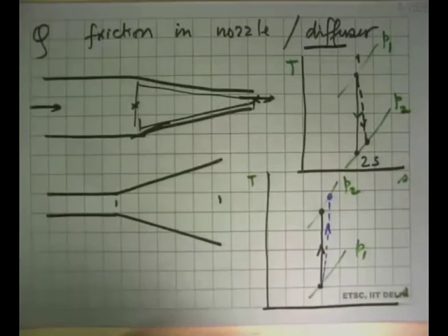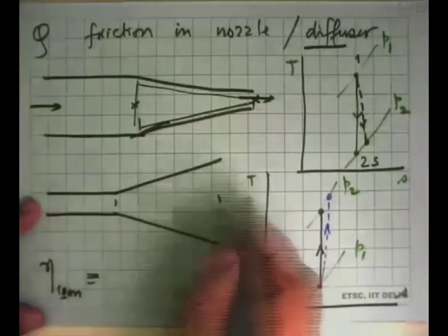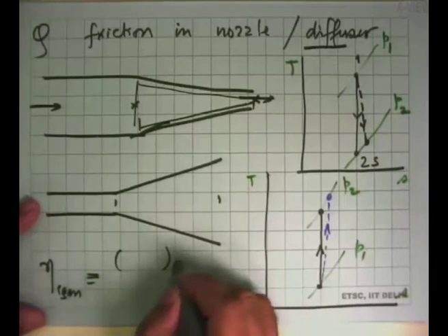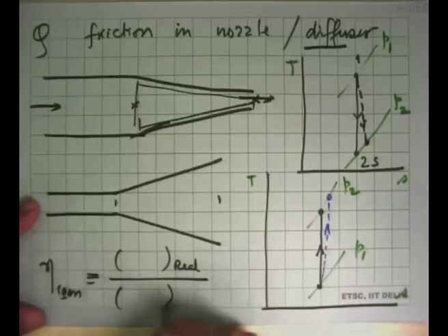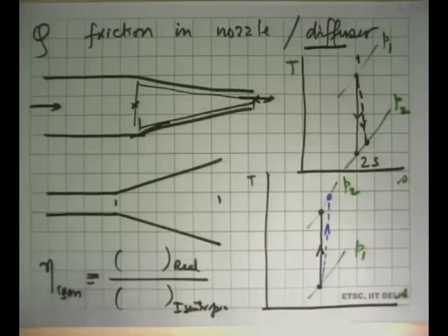And the way we characterize this is the isentropic efficiency, as we defined earlier, if you recall the third module. This was defined in the case of a nozzle as velocity change in the real case divided by velocity change in the isentropic case. In the diffuser, the pressure recovery will be the opposite of that. So that is for nozzles and diffusers. So tomorrow we will look at some design problems of how we make a system, and we'll solve some problems in tomorrow's class. Okay, thank you.